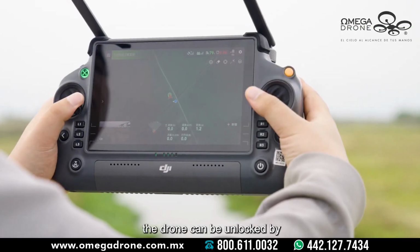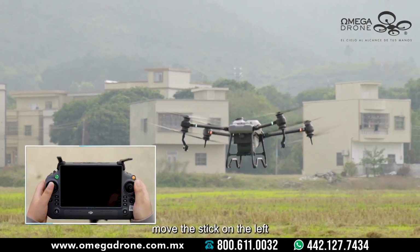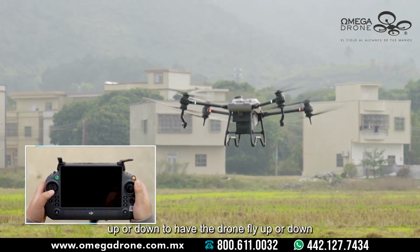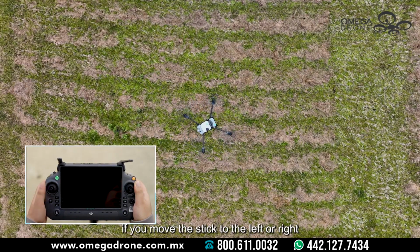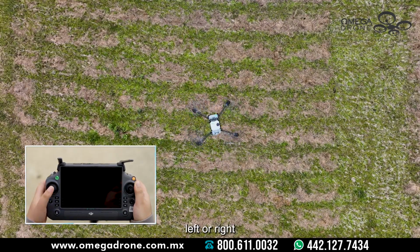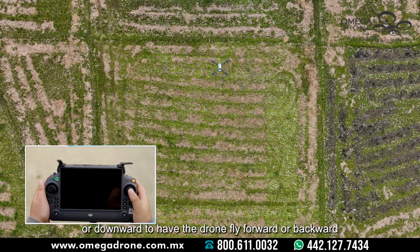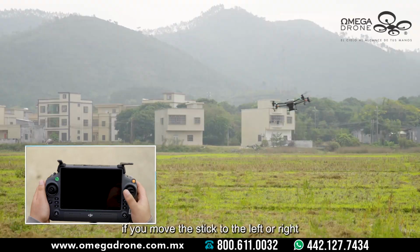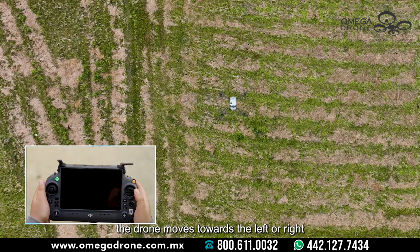The drone can be unlocked by simultaneously moving the 2 sticks towards each other. Move the stick on the left, up or down to have the drone fly up or down. If you move the stick to the left or right, the drone will turn left or right. Move the stick on the right upward or downward to have the drone fly forward or backward. If you move the stick to the left or right, the drone moves towards the left or right.